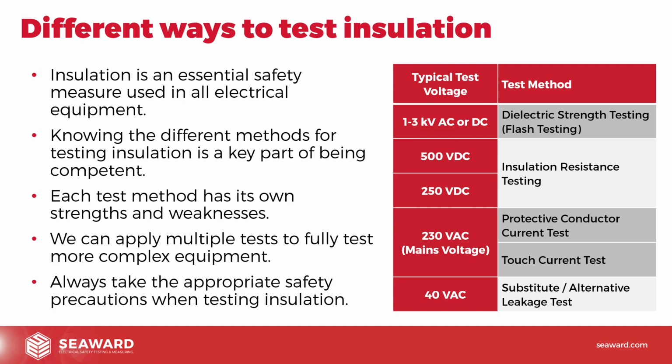Now, again, this is a softer test. We're never going to, or hopefully never going to, damage equipment by supplying its normal mains voltage to it. It's not like we're putting 500 volts in there. We just turn the thing on normally and we're measuring its condition. The great thing with the leakage test, the protective conductor or touch current test, is that they're really just getting the equipment to do what it would normally do. So we can operate that equipment under normal conditions, and we're getting a pretty accurate picture of the safety of that equipment.